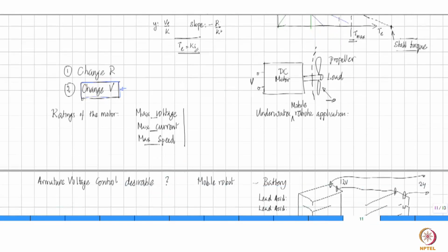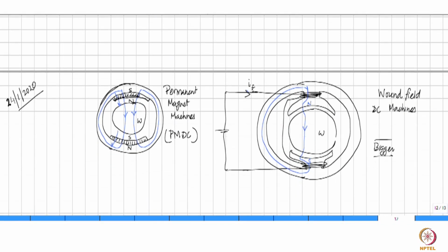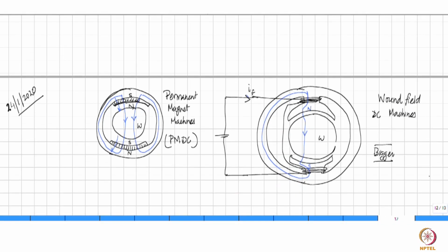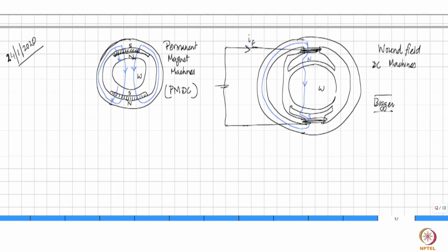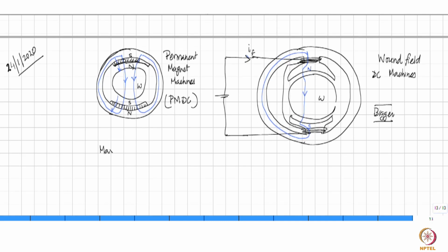Now for a particular design of the armature, when it has a certain number of electrical conductors connected in a certain fashion and so on, as the speed is going to increase, the induced EMF will obviously increase, and the machine is designed to withstand a certain maximum level of voltage, and the induced EMF is going to be simply proportional to B multiplied by omega, right?